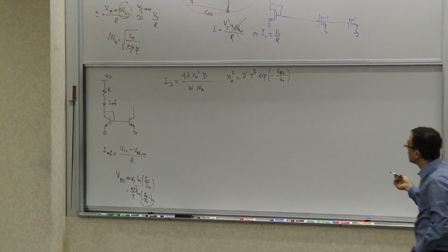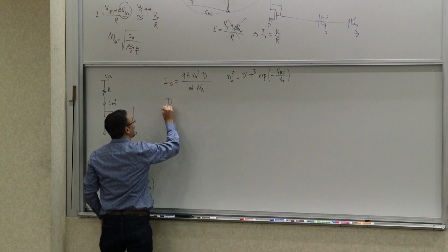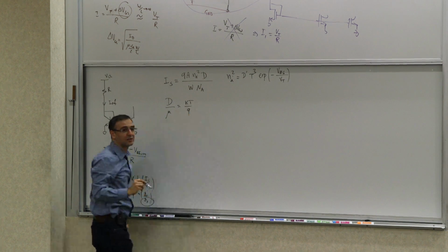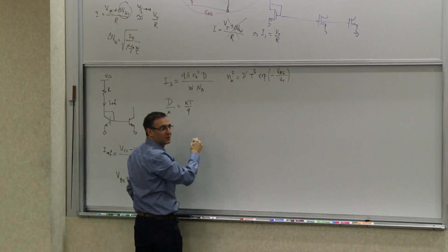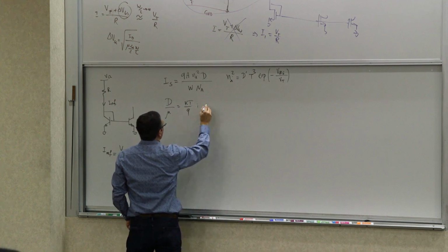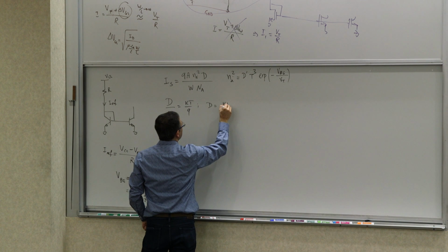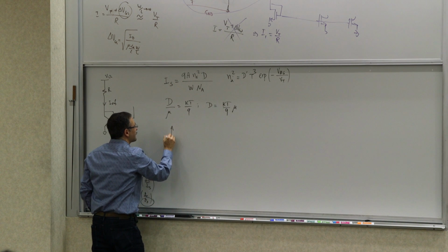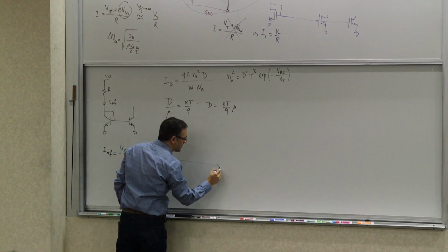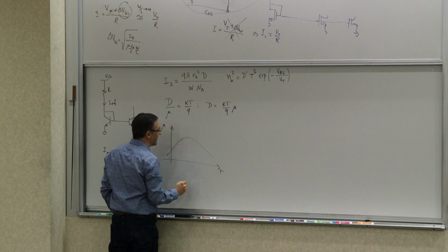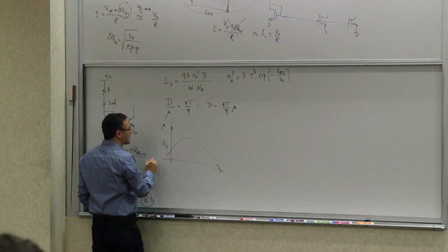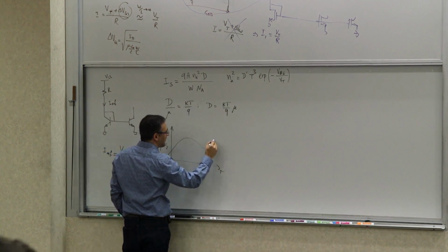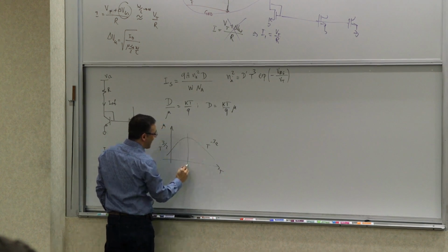There is also another relationship, the diffusion constant. D over mu, the mobility, is KT over Q. And it rhymes. That's how you remember it. D over mu is KT over Q. So basically, D is KT over Q times mu. And mu has a temperature dependence itself too, the mobility versus temperature. Now, this is also pretty sophisticated. It has two regions. There's a region where it has a power of 3/2, and there's a region where it has a power of roughly negative 3/2. This is around 100 Kelvin-ish.